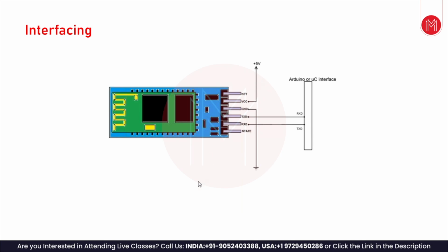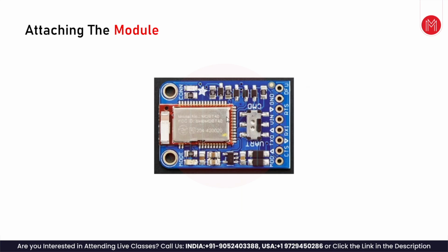Bluetooth modules really come this way, like a stamp module. The PCB has half-cut holes across the PCB edge. They are soldered onto pads on the main PCB. Provision of pads is made here, and the Bluetooth module PCB is soldered onto the main PCB this way.